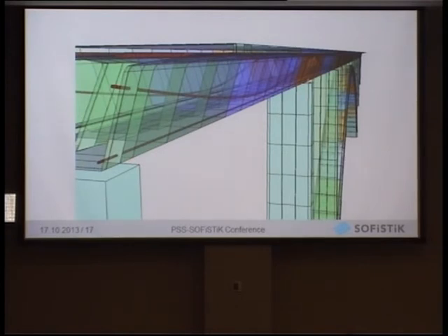We have quite characteristic for a launching bridge. We need a very high centric pre-stress, because for the box girder, the most critical step mostly in launching is when the first element with the launching nose hits one of the first supports. And you will see that in a second when we look at the envelope. And of course, we have continuity pre-stress for the final situation.